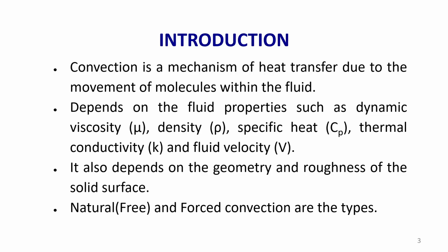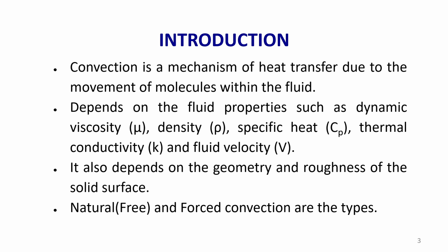And convective heat transfer is associated with fluid mechanics, with properties like viscosity of the fluid and density. So, it depends upon fluid properties such as dynamic viscosity. There are two types of viscosity, one is dynamic viscosity mu and kinematic viscosity nu. The ratio of dynamic viscosity to the density of the fluid gives the kinematic viscosity.